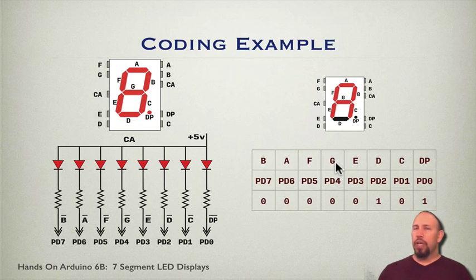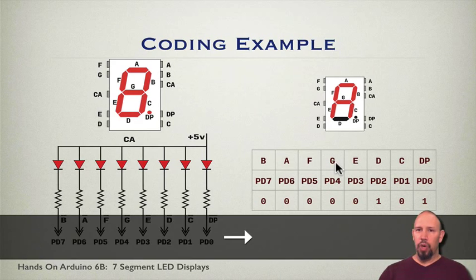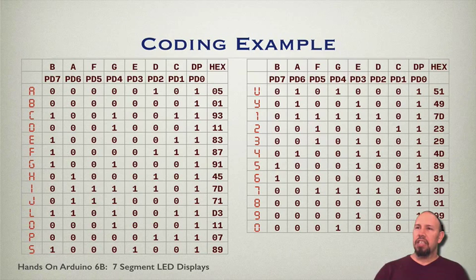Okay, and so we could go through and do letters and numbers, whichever are going to work. Here is a list of some of the numbers and letters for this particular example. So A, B, C, D, E, F, G, H, I, J, no K. It turns out that certain of the letters are not easy to reproduce using a 7-segment display. For example, the letters M and N are not so easy to display.